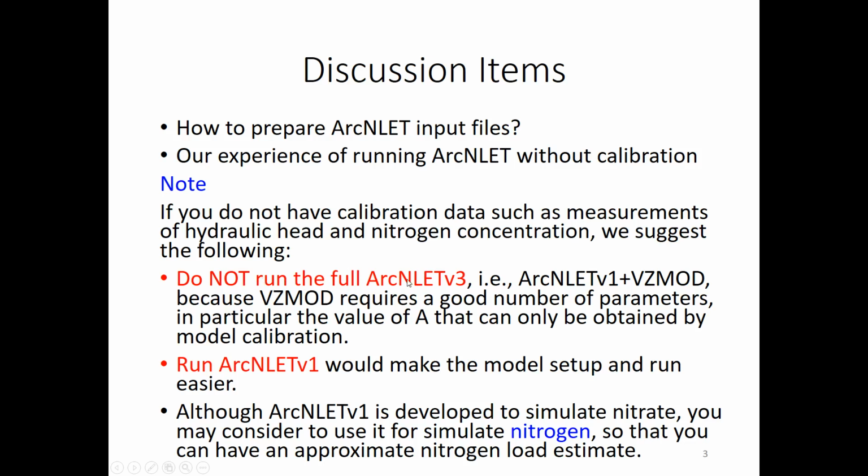not run the full ArcNLET, which is ArcNLET v1 plus Vismod, because setting up Vismod requires a good number of parameter values, and those parameter values are often not quite available. For example, the value of A, which we talked about in the Vismod training video. In this case, you may just run ArcNLET v1, because it's easier to set up the model and run the model. ArcNLET v1, as we discussed before, is developed to simulate nitrate in groundwater.